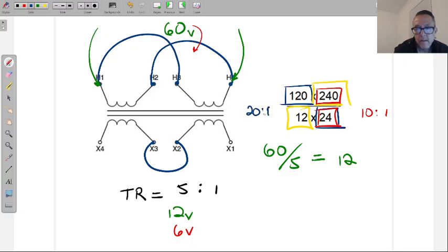How would we make that a step up? So using 3 volts. Bring the voltage bigger on the other side. Yeah, step-up transformers are really just inverted step-down transformers. Every step-down transformer, normally that's what we're working with, if you connect it incorrectly, will be a step-up. And instead of dividing, we would multiply the turn ratio, right? Correct.